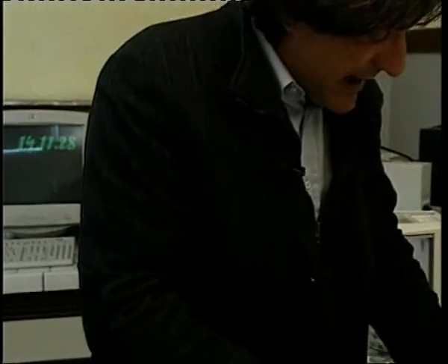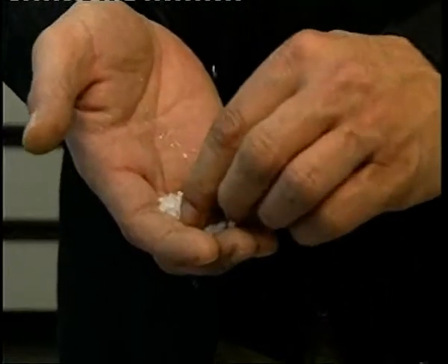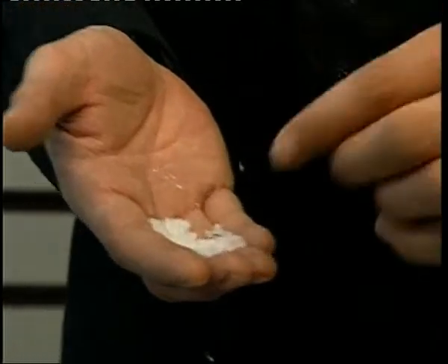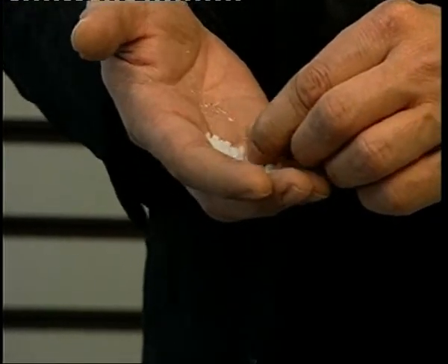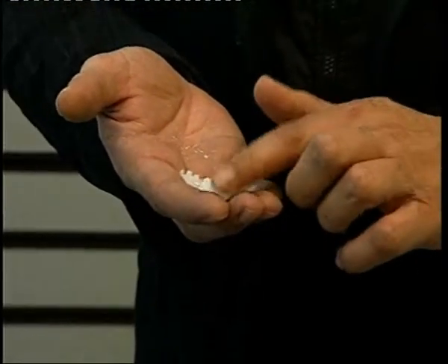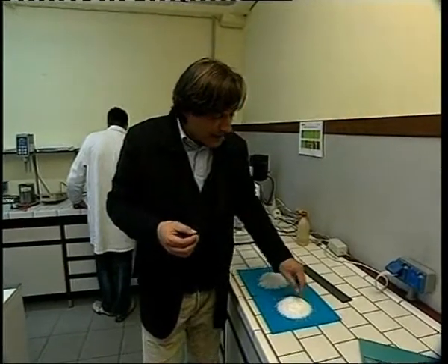The second family of modifying resins is known as APP, or atactic polypropylene, a byproduct of the process used for the production of polypropylene, a component of many products that we use every day. This resin gives the membrane better mechanical strength and flexibility. Resins are fundamental, but not so much the quantity as the quality and the constancy of their characteristics. Because, as I said before, a bituminous membrane without resins would have a very short lifespan.